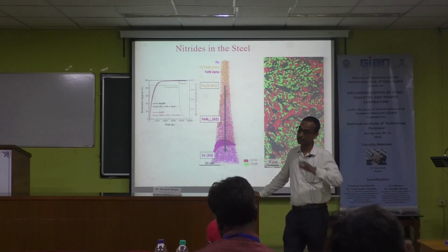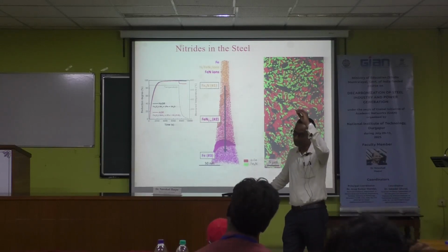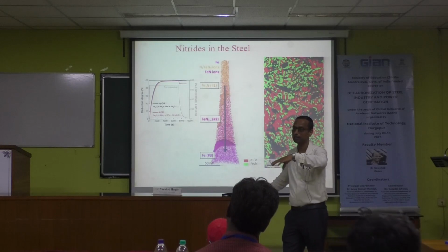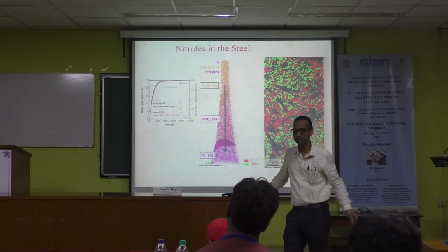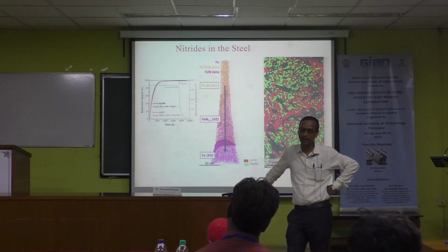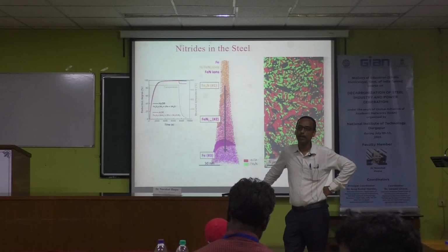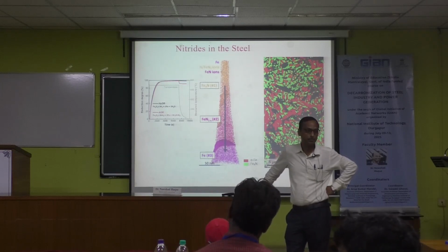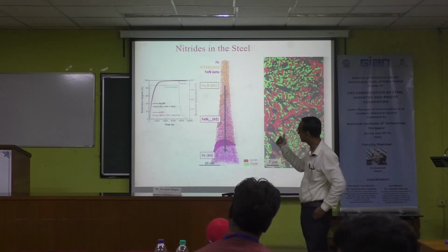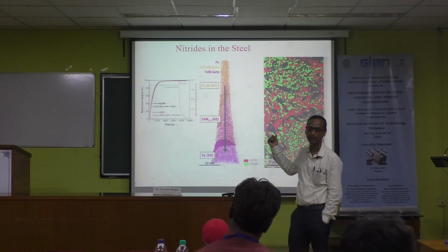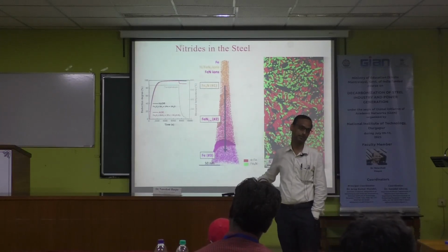If you introduce nitrogen in stainless steel making, you will replace the nickel, meaning the nickel requirement will be less. At that time, you have to add some manganese. So for nitrogen-carrying stainless steel production, this DRI will be beneficial.